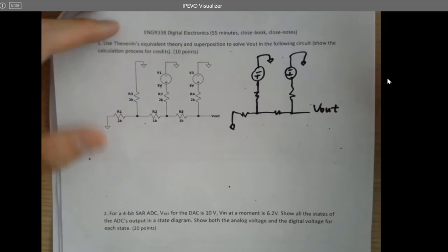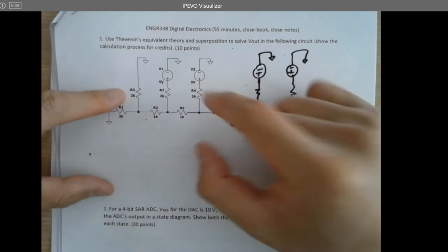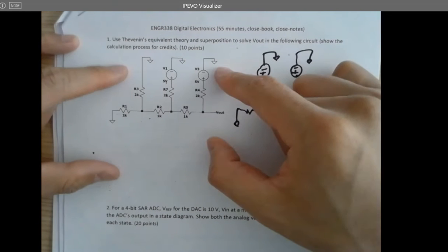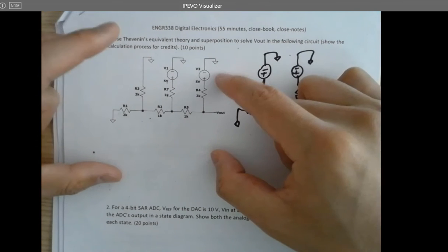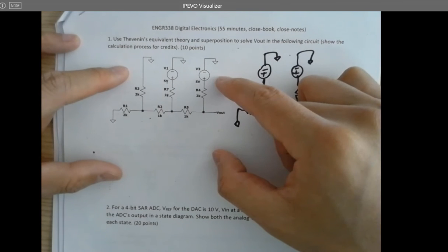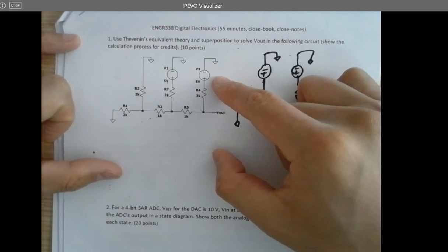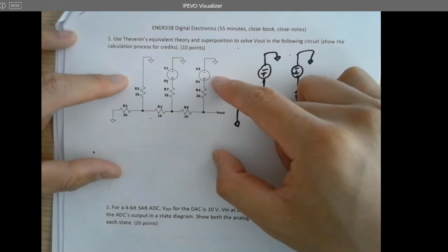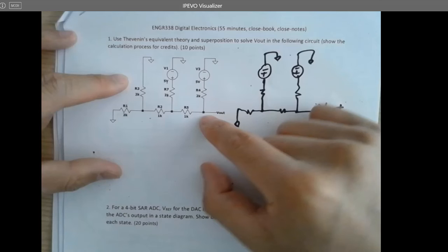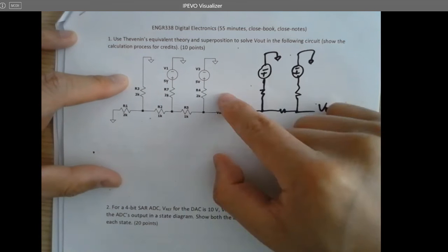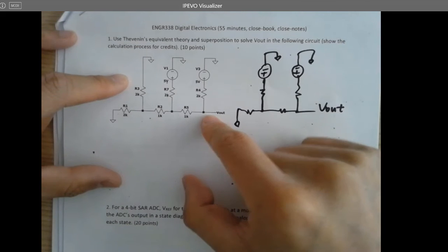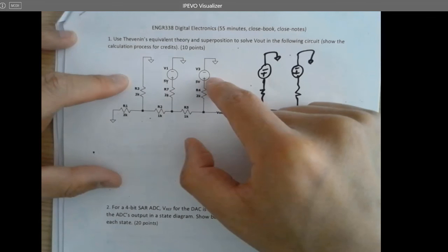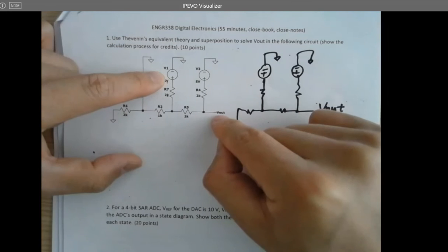Yeah, another question. Which one on this R2R DAC is MSB? Where is LSB? And why? Because this voltage is not being divided by that many resistors. So you are getting a higher voltage here from this guy. That's why this is MSB, because this 5 volts contributes a lot more compared to how this 5 volts contributes to the VL.